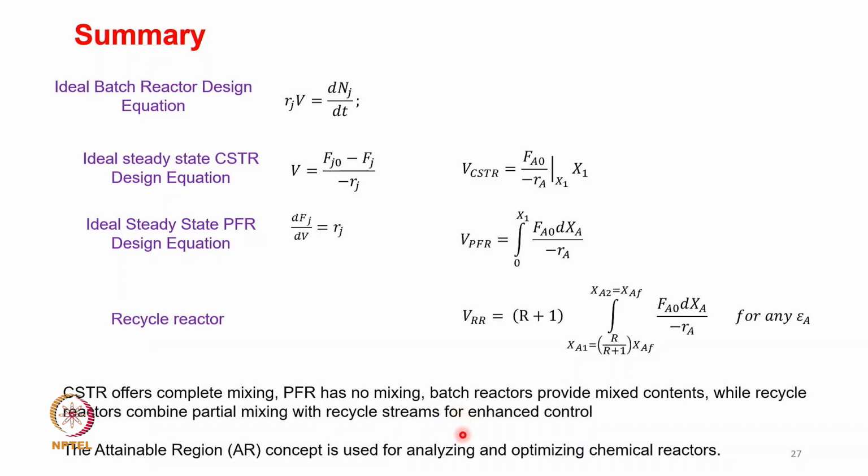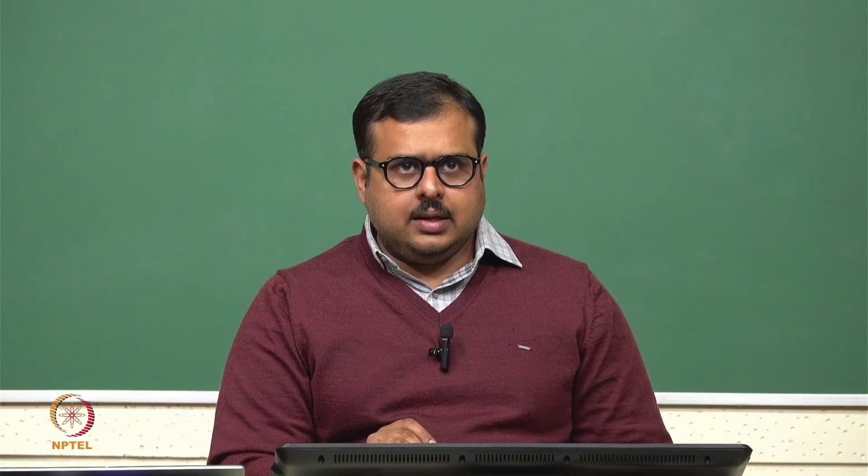Qualitatively, we may say that the CSTR offers complete mixing, the PFR has no mixing at all, and the batch reactor provides mixed contents, while the recycle reactor combines partial mixing with recycle streams for enhanced control. By tuning the recycle, the recycle reactor may behave like a plug flow reactor at one end and a CSTR at the other end.